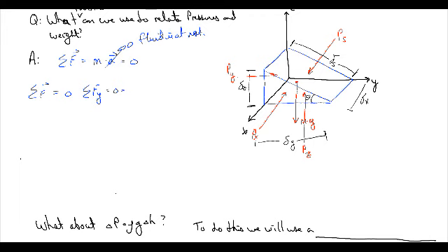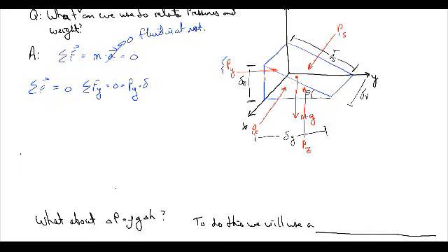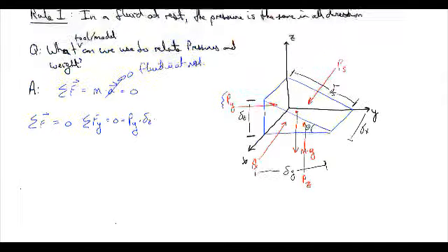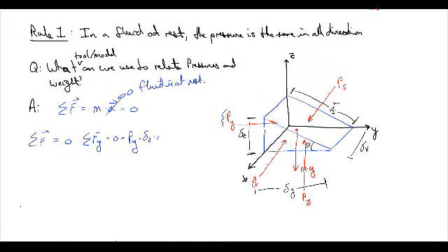and now if we do that, we know that this pressure in the y direction, Py, is acting in the positive direction, so we can just leave it as Py, times an area, which is going to be delta z times delta x.